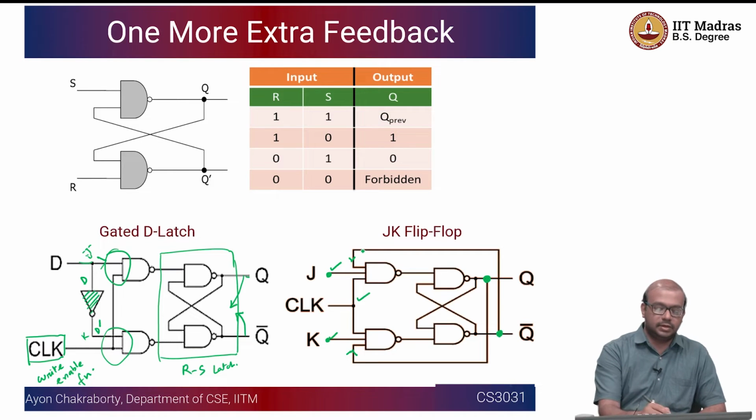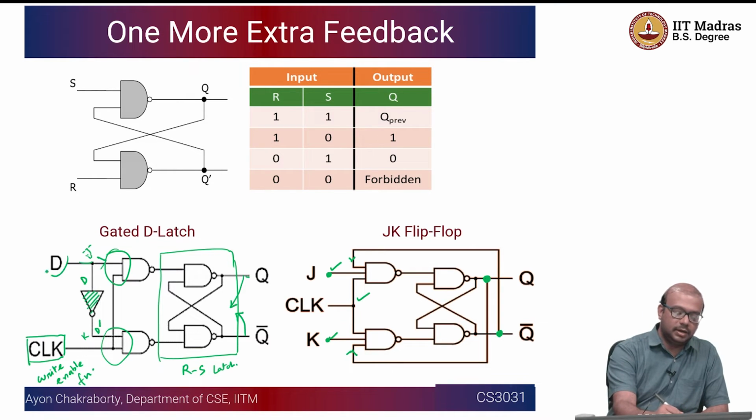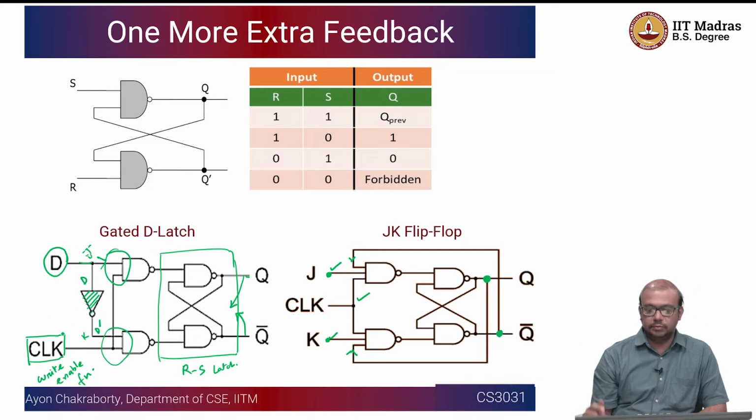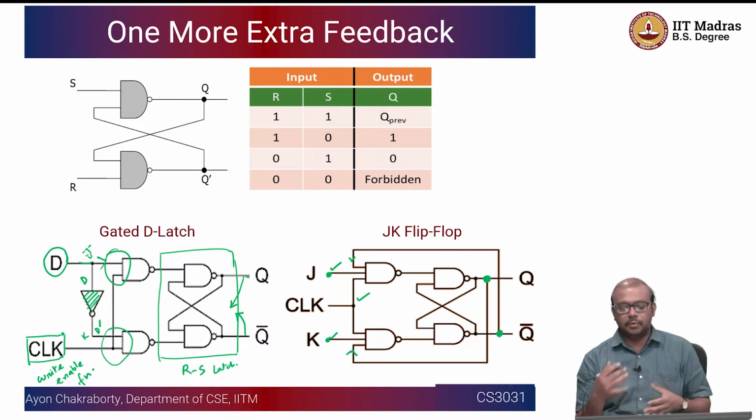Here the clock was itself used as a write enable function. Here we can see, if you have a value in D and your clock pulses through, if the clock is high, it is going to write data during those periods of time. It can be done in a little bit more sophisticated way.